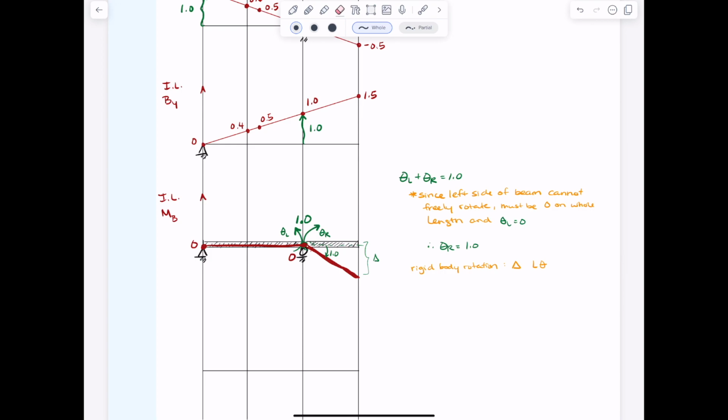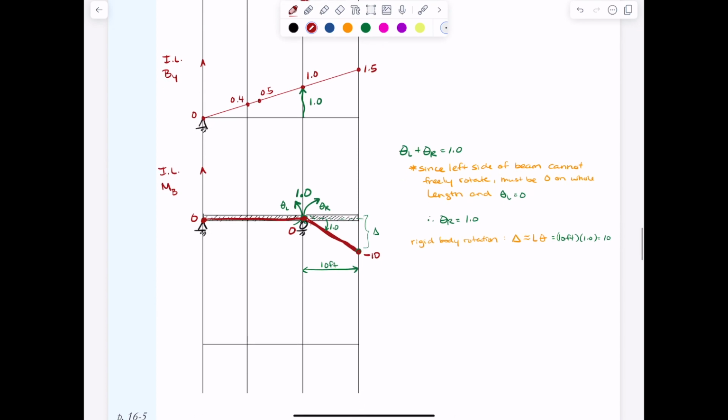So just keep in mind, if I use this influence line, it's going to give me kip-feet or something as I move that load across. And because it's down below the structure, as I drew in that rotation, it's a negative 10. I drew in that rotation in the positive direction according to our sign convention.